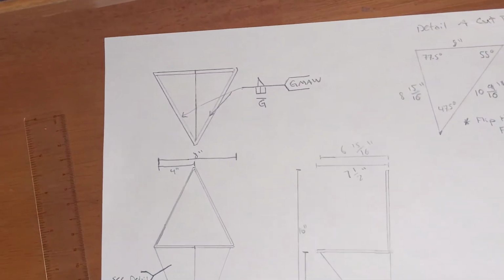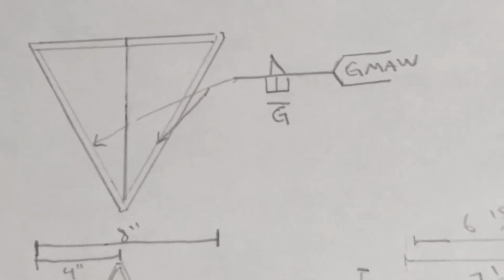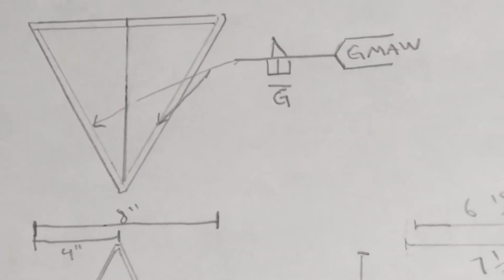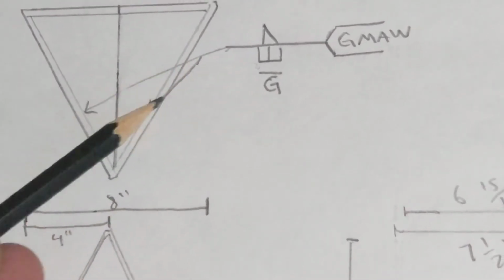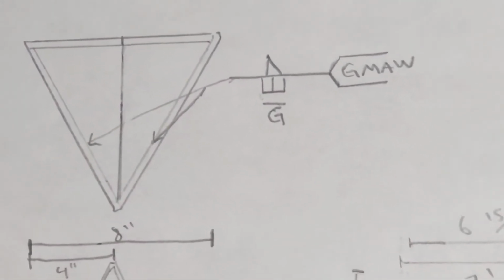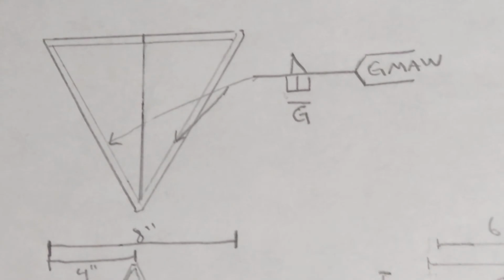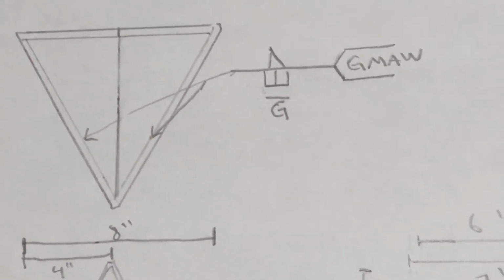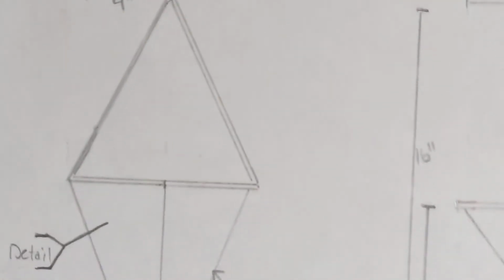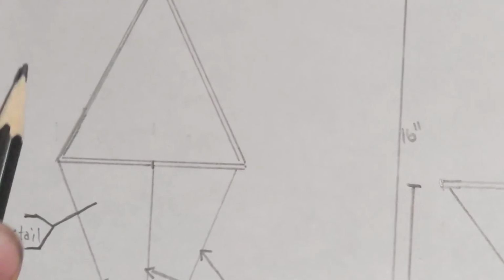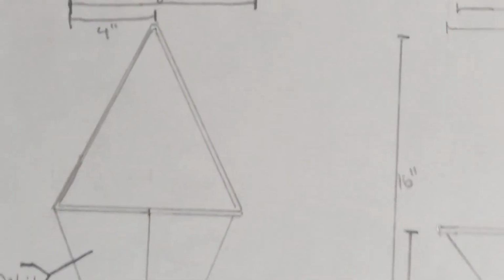We also note, if I look in my top view, I gave a weld call out for both the arrow side and the other side. See, on this side we have it on the arrow side. We have an edge weld because I have flat edges between that round bar and the edge of that sheet metal. You may even call this a J groove, but we'll go with an edge for this example. But I also have on the other side a fillet weld. So where that actually is translating to is if I come down here in the front view, up underneath that round bar, I went and put a fillet weld all the way underneath that, okay?